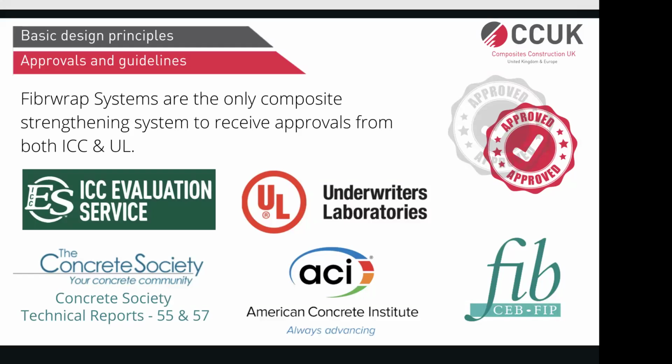Now, in terms of design, if we're designing it in the UK, then the document to follow is this Concrete Society document TR55. That's the design guideline to design FRP in the UK. There is ACI 440, the American Concrete Institute document, majorly followed in America and worldwide. So I presume if you do a project in South Africa, you'll probably end up designing it based on ACI. And FIB Bulletin 14 is followed in the rest of Europe. So these are the three main design guidelines which are used worldwide to design FRP.